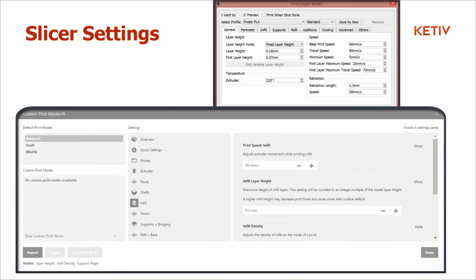Slicer settings. People will wonder, what settings should I put my printer at? Usually I left it at the default, besides the fact that I changed the density. The temperature remains the same. You might have to toggle the temperature depending on the type of filament you have. But for the most part, if you have a good setting for your printer, just leave it at that.